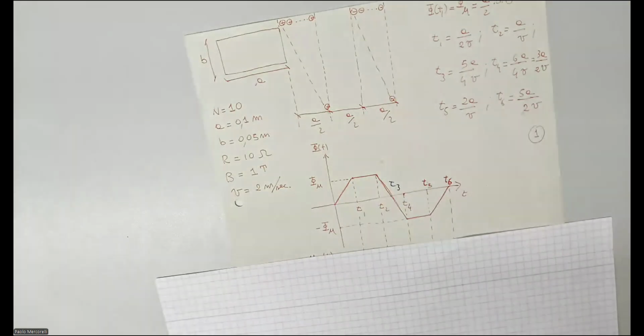In the negative sense. Now I am moving from left to right. Try to imagine. On the front of the movement, we include negative flux in this coil. On the rear part of the movement, we exclude positive flux. This means you have a double contribution in the negative sense. We are going down with a slope twice the slope with which we are going up.